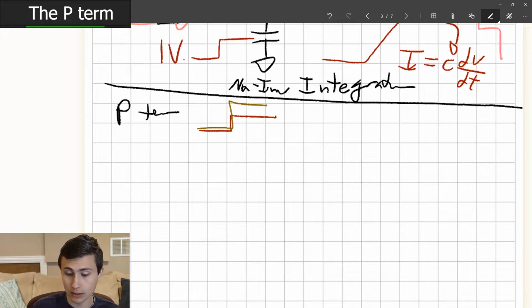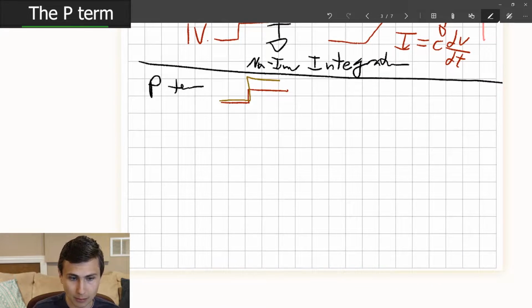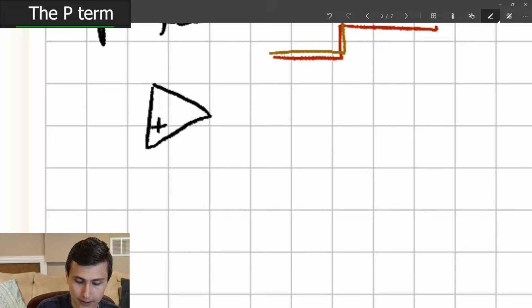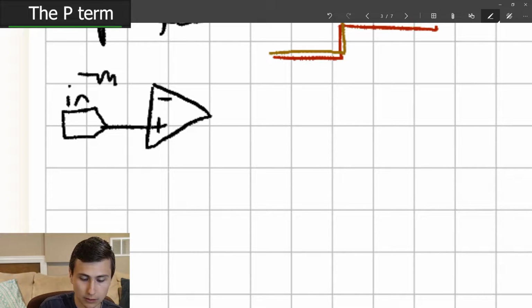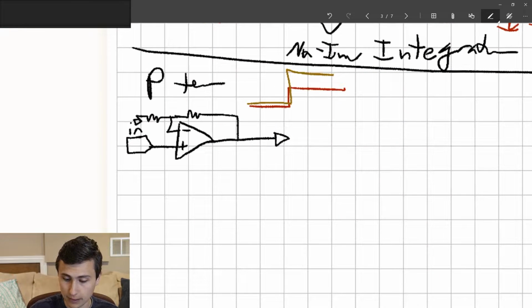Well, if we're going to keep everything non-inverting, we just build a simple non-inverting op-amp amplifier. It's really that easy. We do that with a positive and negative input. The positive is directly our input. The negative term has a resistor going to ground. Ooh, running out of space. And then the resistor coming around to the front. Then that's our output. Phenomenal.